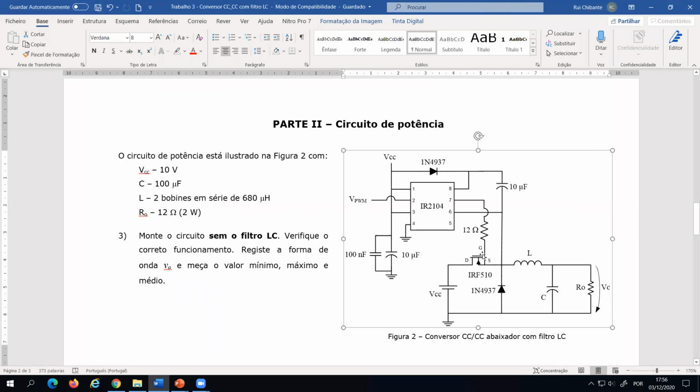So you are using a MOSFET, okay, with the terminals gate, source, and drain, okay. As I said before, we must apply a control signal between the gate and the source, okay. But the problem is that the source terminal is not at the ground terminal, either of the power part and the control part.